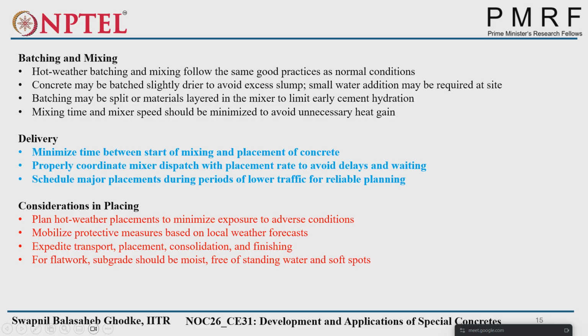Plan hot weather considerations in placing. Plan hot weather placements to minimize exposure to adverse conditions. As we saw in cold weather, the subsurface should be properly cleared of ice. Similarly, in hot weather conditions, the subsurface should not be too hot, so we have to be careful. Here the temperature condition has not been given like the cold weather condition of 2 degrees Celsius and 5 degrees Celsius, but we have to be careful. The surface should not be way too hot compared to the concrete temperature.